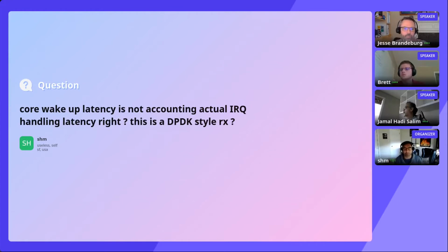So that 40 microseconds is just C state switch to C0 and then potentially another 10, 20, depending on how badly your interrupts are being held up and everything else, right? So yeah, I was simplifying a bit. That's an average, right? Depending on the processor's state and how long it's been in a sleep state and a whole bunch of other things, it can take all over the place. It's a histogram, right? So the histogram top point would be the 40 microseconds.